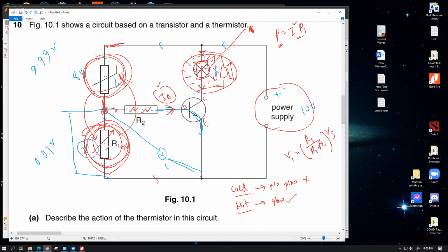For example, let's say I want to run a cold storage where I want the signal for 4 degrees Celsius, and the scientist who is doing some laboratory work wants a signal in their science chamber where the temperature should not go more than minus 25 degrees Celsius. So it should be always below minus 25. So they can fine tune this resistor value so that this whole thing can work at minus 25. So it will not give you a signal if the temperature is below minus 25. Whenever it goes up, it will give a signal.